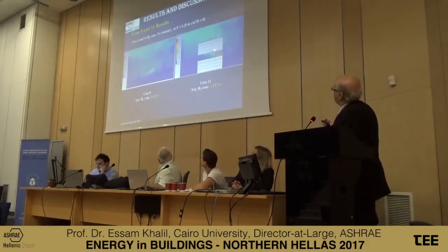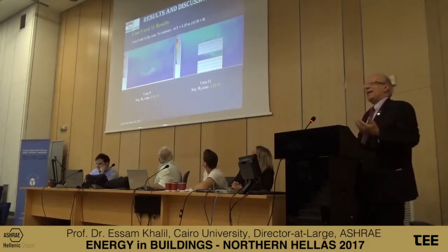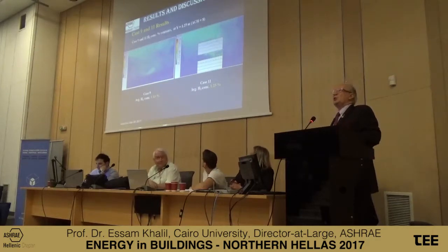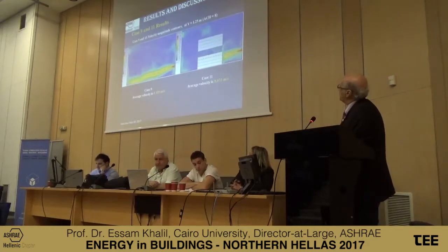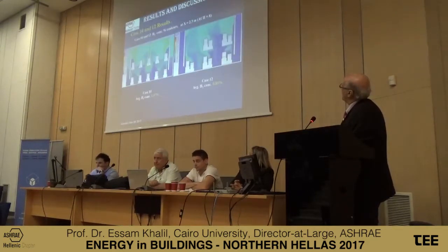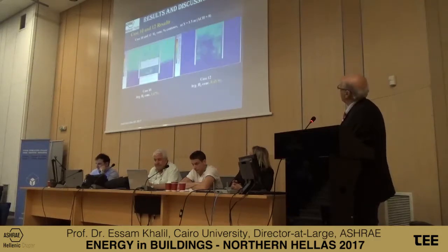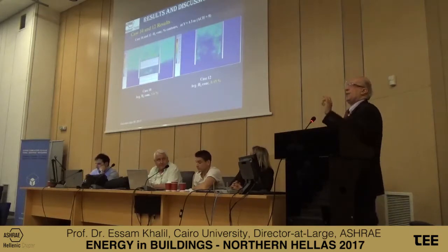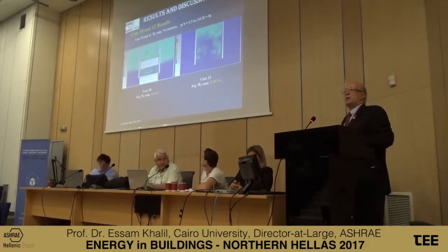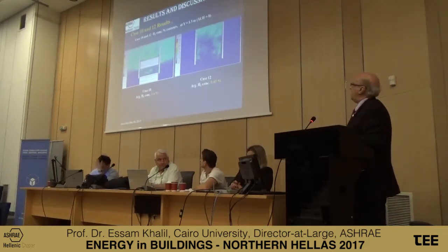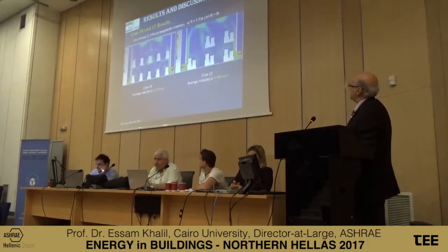Here the details. It's basically a fluid dynamics case with the concentration. So you're solving your continuity equation, momentum equation, and also the concentration of the species. So it's all the same but different application, different air change rates. So if you look into any of the ASHRAE guides, you will find that for each particular case, you have the recommended air change per hour, and it is being tested for various cases.